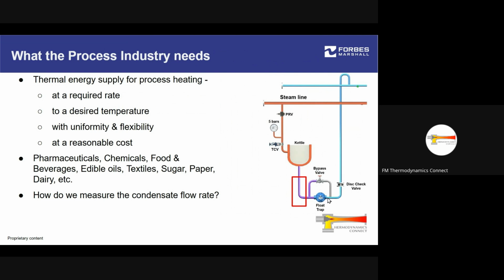So the outlet has to overcome this much of a vertical rise in terms of the water column. That can give rise to some pressure. There may be some equipment like a disc check valve or something. The pipe length itself could be longer. There may be bends, etc., which will provide some form of a back pressure.